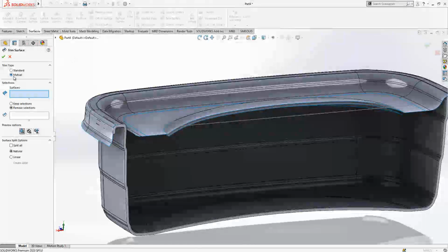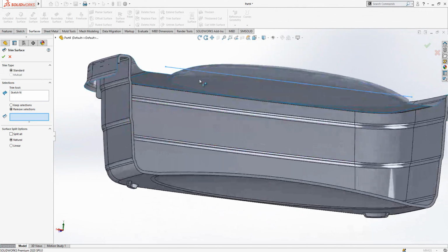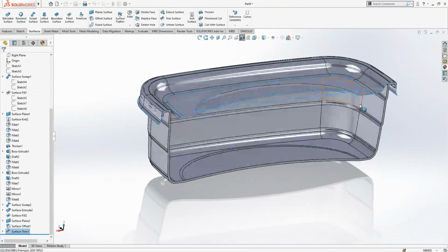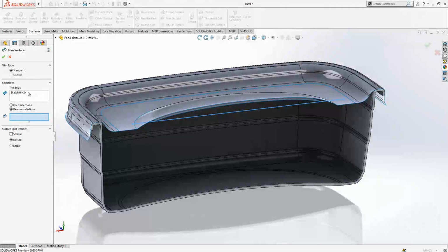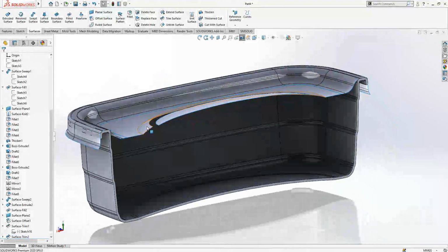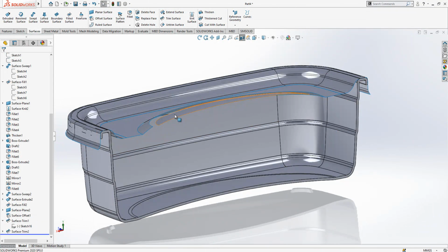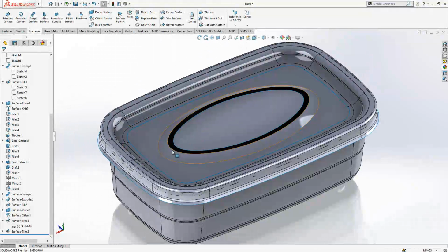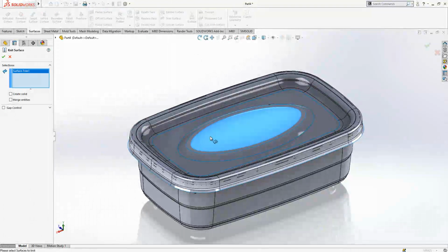Sketch is selected. I go to trim, then I change it to mutual standard, and then remove the selection. The program says this one. I remove the unnecessary part. Now I select again my sketch, standard, and I select this one. If you see what has been removed, the upper part of this surface, if we visualize them, first we cut the surface below that 2.5 millimeter line, and then the upper part of the outer surface, and then the planar surface should create here a planar surface for me, and I will add knit,